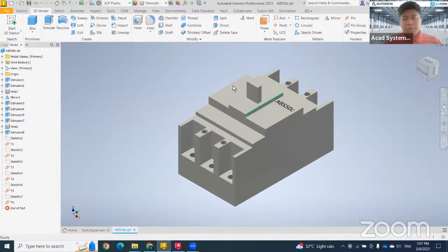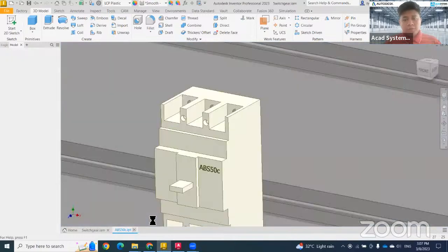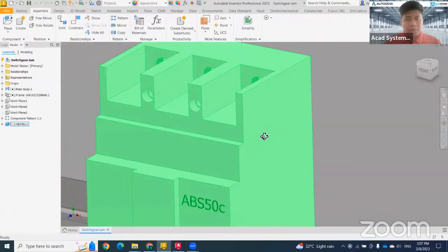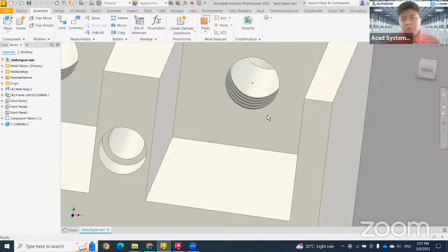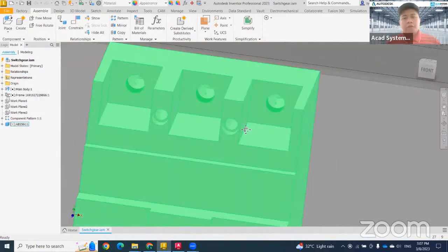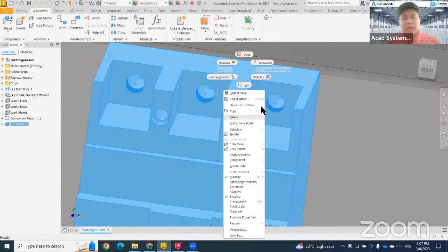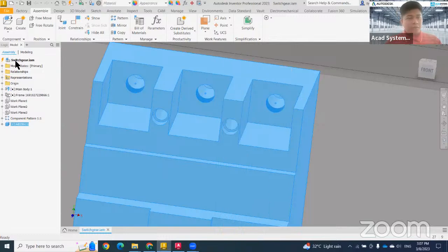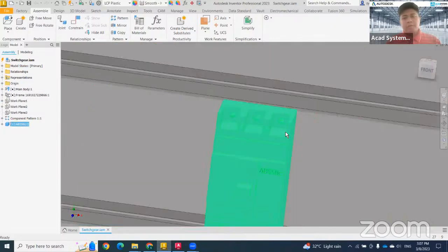Done with the first model, you can just close. What happens now is that when you zoom, you will see that your model has this kind of point, which is an electrical pin. If you click your model and right click, right now you cannot see any electrical properties yet, because we did not do any linking and we did not do any harness in our 3D model. So right now it's a very rigid 3D model.